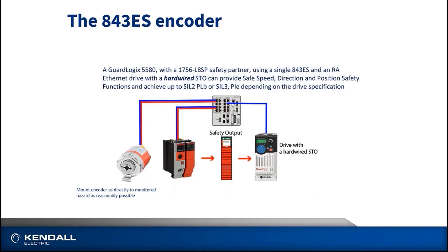We can also take safety outputs from our PLC and integrate them into any drive with safe torque off. The safety rating of the application will be determined by the safety rating of the drive, so either SIL 2 or SIL 3, depending on the drive. Even though the encoder is SIL 3, the drive is going to dictate which safety rating we have.